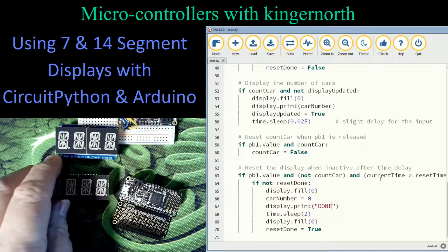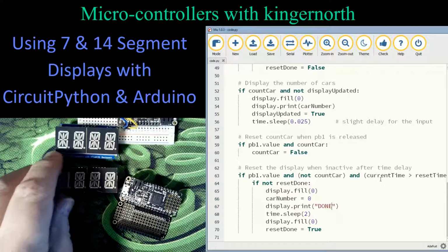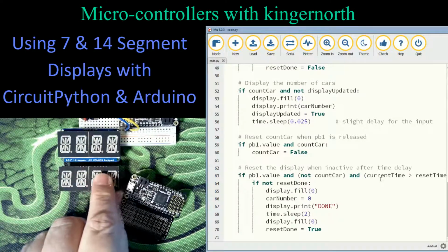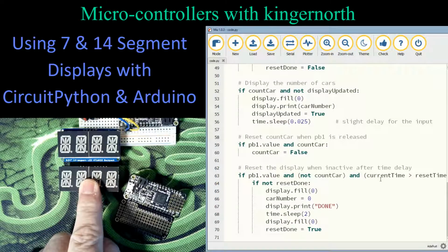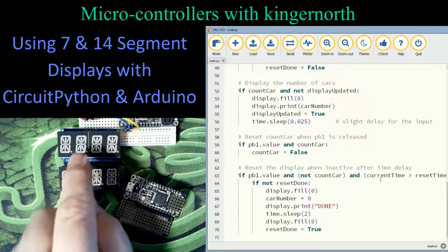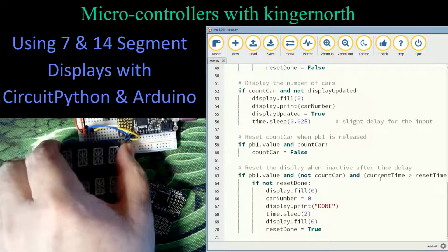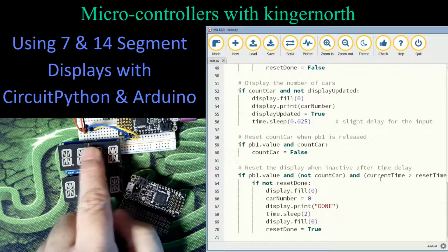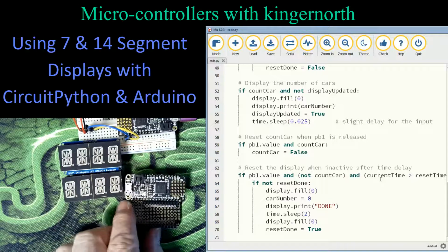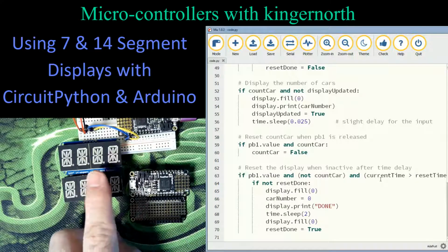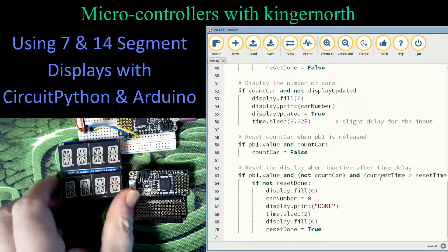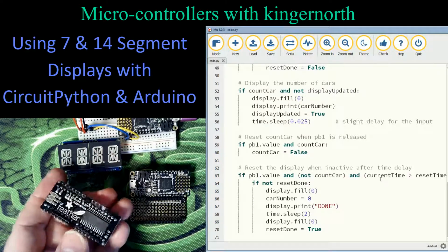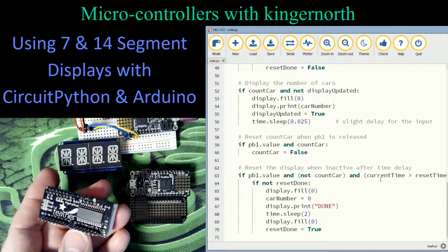This display, these two displays are identical. In fact, they have the exact same modules on them. They both have the same drivers. It's an HT. It works exactly the same. The difference is this one here only has the pins on it, the standard little pins. So it has the I2C. It only has the 5 pins, 2 for power, 1 for common, and then the 2 communication pins. Whereas this one is set up in the feather format, so it uses all the feather setup already.